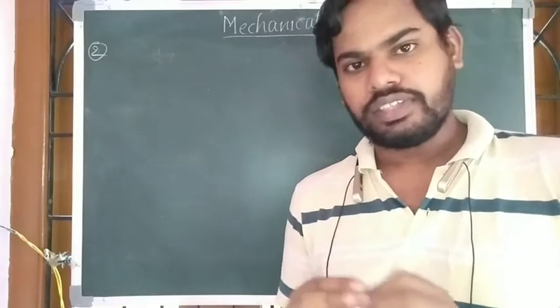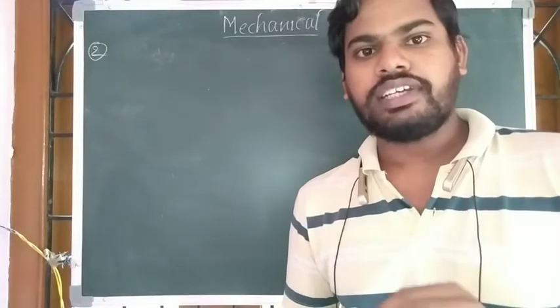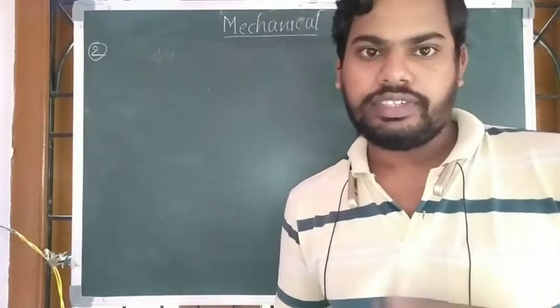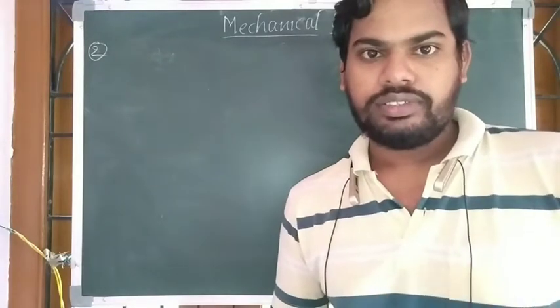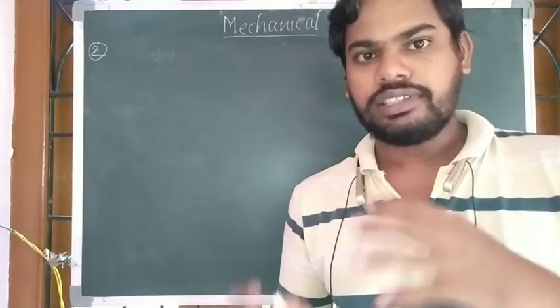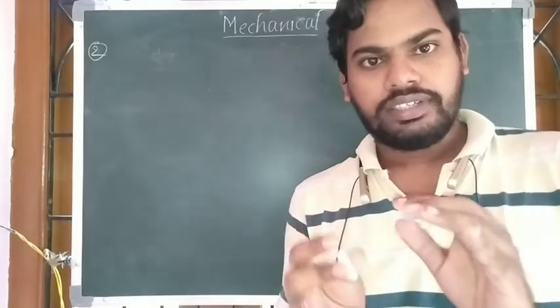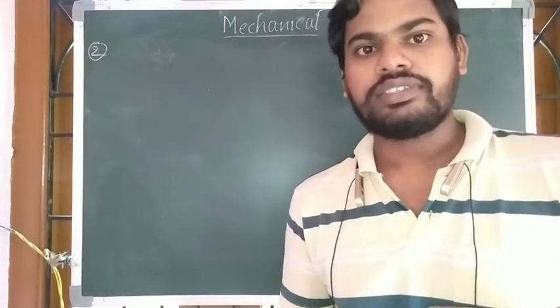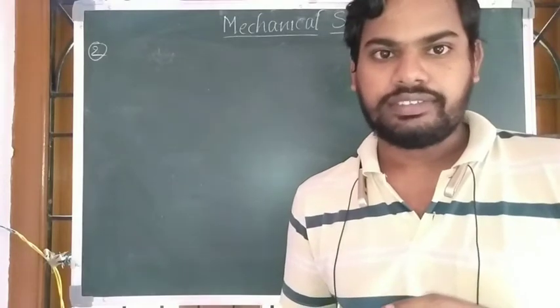Now case 2, where we consider the curvature effect. If we consider the curvature effect, then Ks becomes K, where K denotes the Wahl's stress factor.